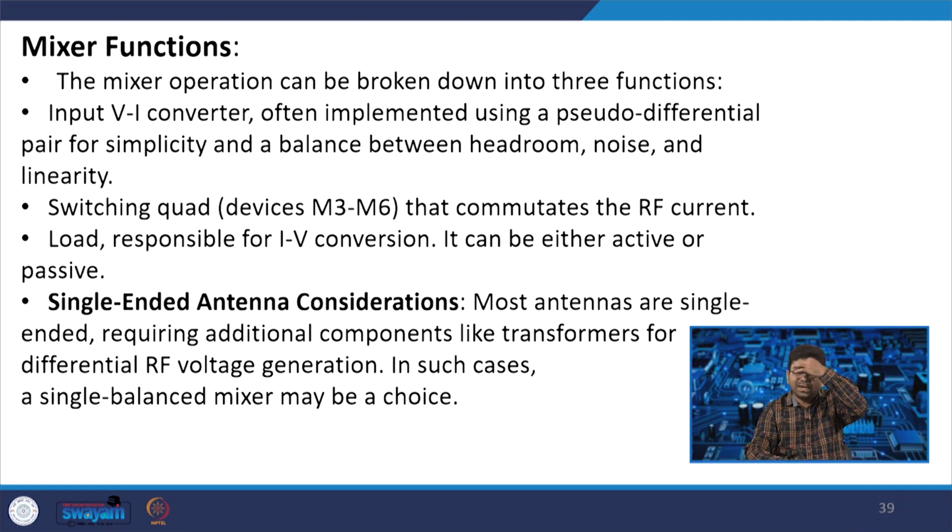There is one important thing: because this is a differential signal, and the antenna is mostly single ended, in that case you need a single balanced mixer.